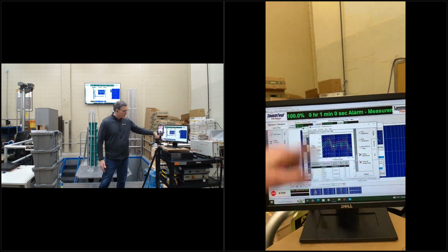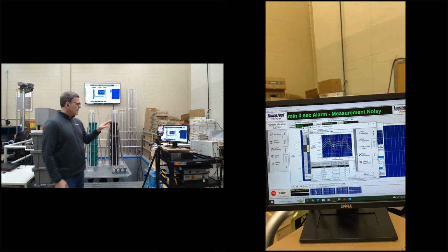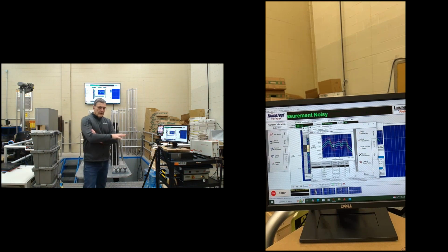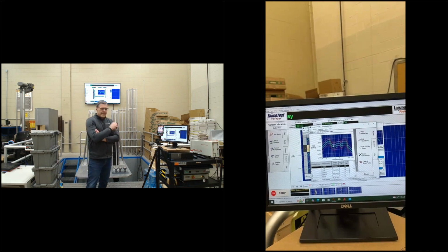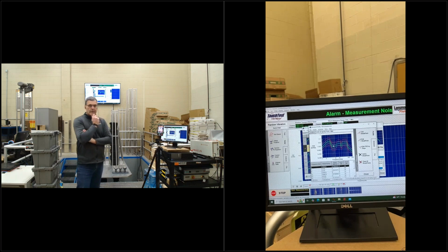So if I have to deal with it, I would rather design my system to respond in the areas of comparably less energy input, if that makes sense. Because I can't avoid it. I have to ship it. I have to use leaf spring trucks, but I'm going to try to get a natural frequency in the 6 to 10 hertz range versus anything outside of that range. And that would be one way of dealing with it.